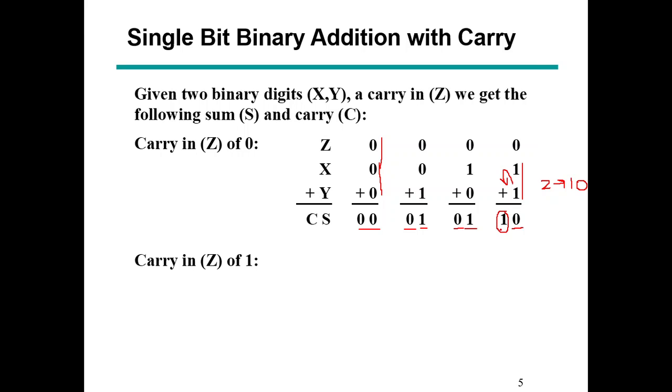Although you can say 1 0 is the sum, why call this part of the sum a carry? But here the sum, y, x and z are all single bit. And when you add 1 plus 1 you get 2, so 2 cannot be represented in a single bit, so there would be a carry out, there would be overflow.